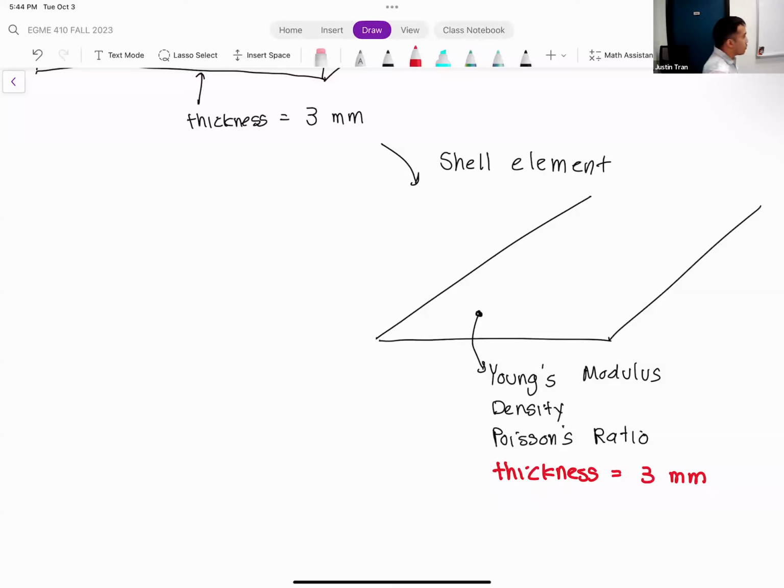And so if you think back to activity 3, actually, that strip that we used to apply that wind force on the side, that was essentially a shell model, right? We stuck it to the end of the signpost. And remember, one step that we did was we manually assigned the thickness of that shell. Okay. At that time, we assigned the thickness to be very, very small because we didn't want it to affect the structural properties of the signpost. But in theory, you can set that thickness to be whatever you want to represent that shell. Okay. All right, and so we'll talk about how we can assign that thickness because there are multiple ways to do this.